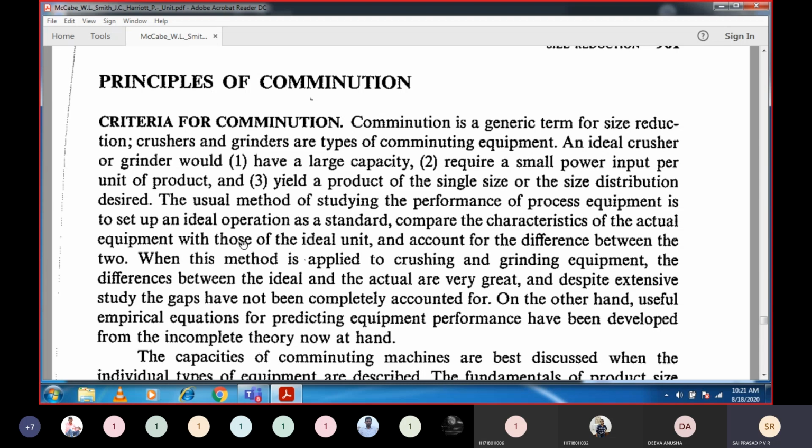We bring the second. What is the second equipment? The second equipment operates on the mode of impact. The third may operate on the mode of shear forces. Like that, we select them and then conduct the experiment. So the first step is what? We are supposed to conduct experiments and see in which system we are getting the maximum amount of Xi. What is Xi? The mass fraction of solids in the given sample.